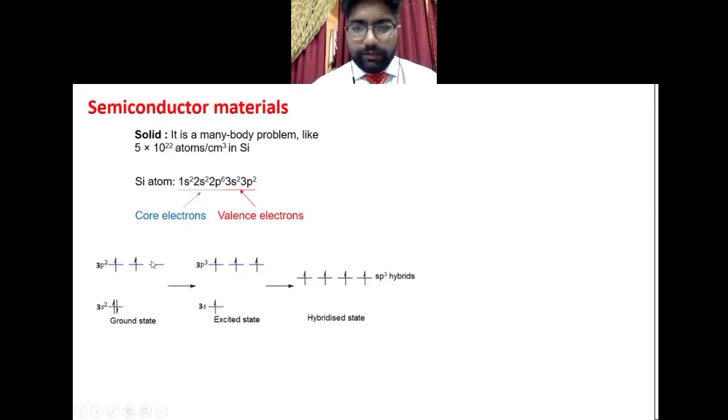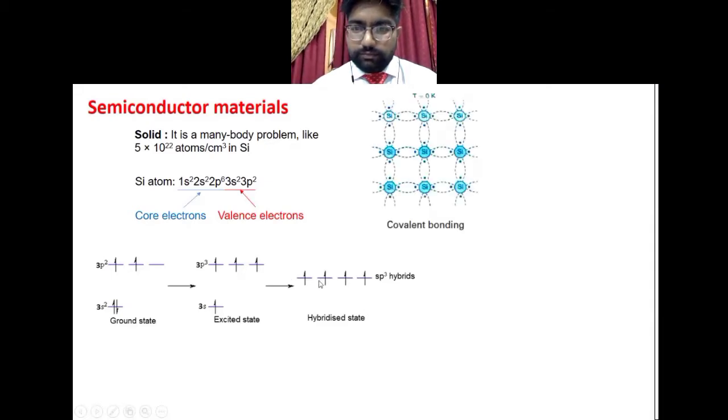So then you will fit these IV characteristics, try to find out the built-in potential for the PN junction, you will find inaccurate values. So it is very, very important actually. This is what I say, because I am working in semiconductors. So I know, if you want to find out very accurately the properties of your semiconductor material, you should always try to make a very good ohmic contact. That is the starting point.